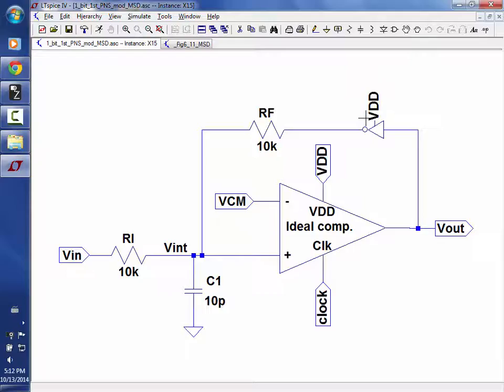Okay. Are there any questions about this circuit? Does everybody understand that if I flip the plus and minus on the comparator, I would invert the signal and not need this, but then when I did the digital filtering, the output would be inverted? We don't have enough time, but if you want to, you can do it on your own. Okay, no questions on this circuit.